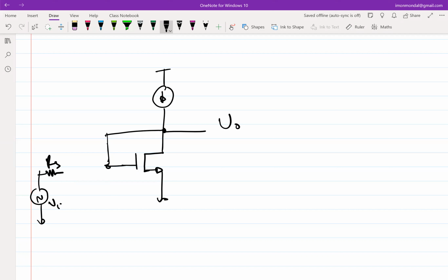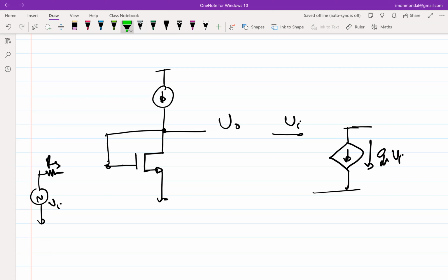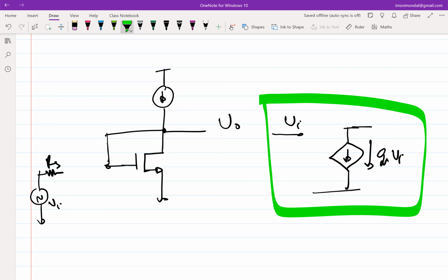So now tell me, how should I go about connecting it? Because ultimately, see, what is the small signal picture that I am looking at for this amplifier? The small signal, or the incremental picture, that I am looking at is your Vi should appear here, and this current should be GM times Vi incrementally. So this is the picture that I am looking for. But I have this transistor which is biased with the constant current source like this. So how can I superimpose this incremental picture onto this transistor picture, or the biasing picture, right? So this is how I have biased it up, but now I have to apply an incremental voltage source and take the output.